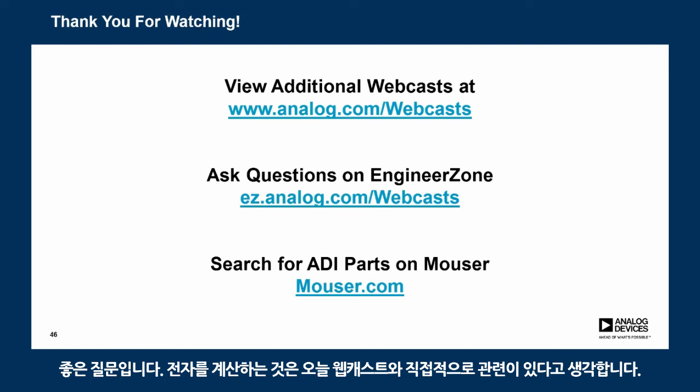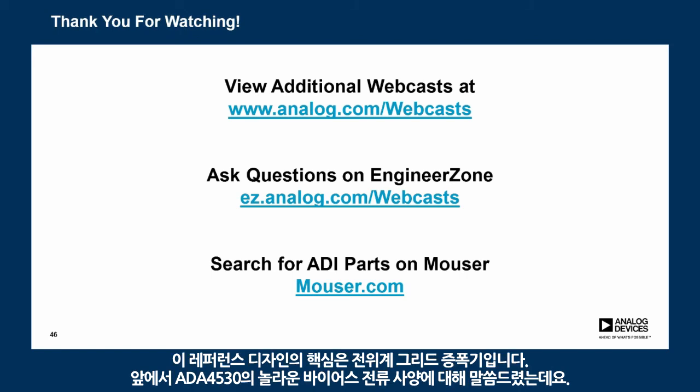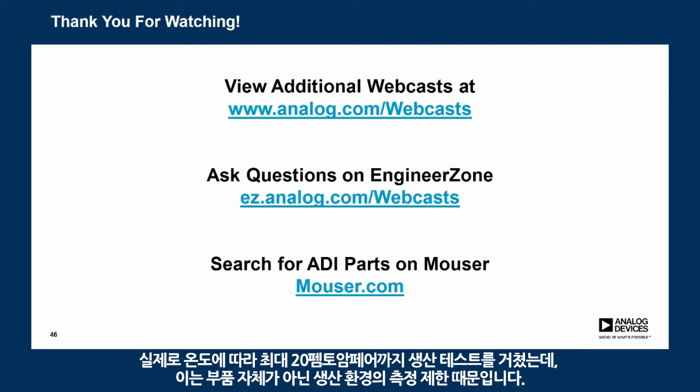That's a very good question. I guess it pertains directly to the title of the webcast, Counting Electrons. The core of this reference design is the electrometer grade amplifier. I mentioned earlier the spectacular input bias current specifications of the ADA4530. It's actually production tested up to 20 femtoamp and over temperature, and that's also because of measurement limitation of the production environment rather than the part itself.